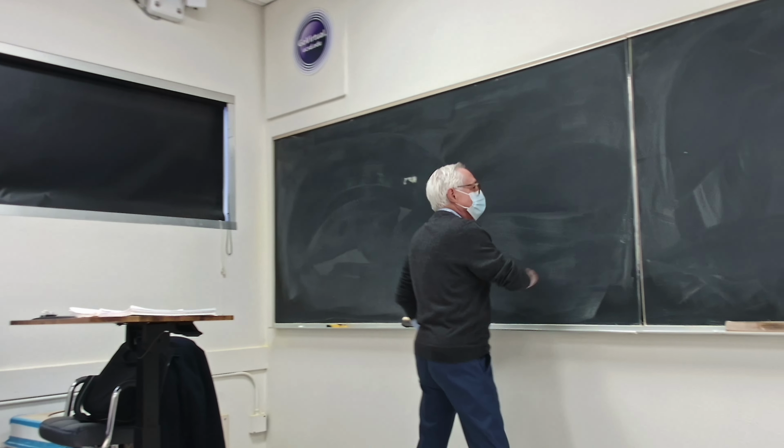Okay? And I know the other conditions. Enthalpy at the inlet and exit for A. Right? Velocities, if given, fine. If not given, fine. We don't care. Z, elevation is insignificant. Therefore, you see that just with enthalpy and mass flow rate for A, and mass flow rate again for B, and H exit, H inlet of B, I can balance and find the Q dot from one to the other given them. Okay?